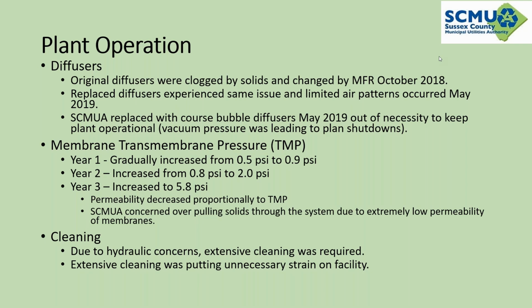That led to those diffusers being packed with sludge, which led the membranes to be very heavily dewatered. Then there's a big drop in the membrane permeability, which all correlates back to the failure of the diffusers.